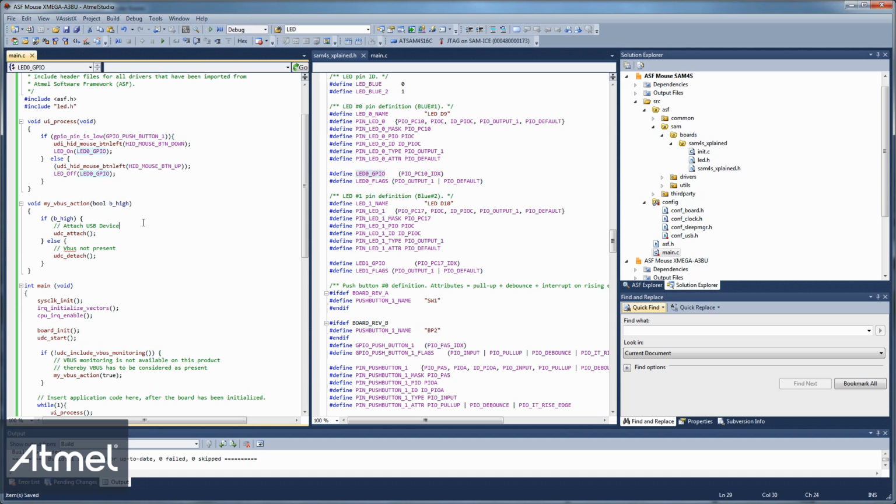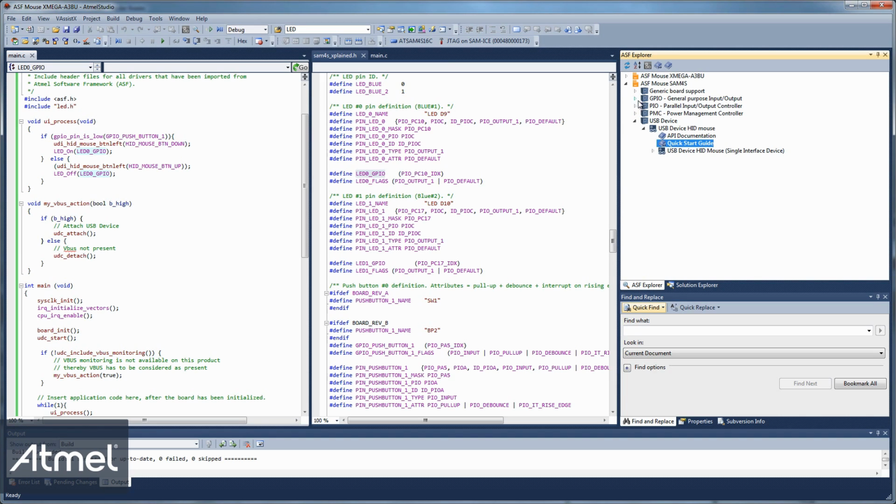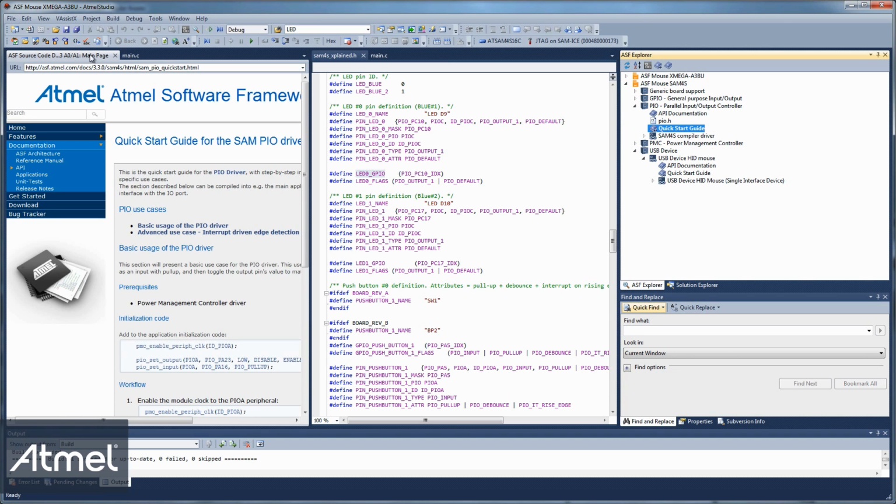In the XMEGA, no special initialization is required before we can start using gpio. The XMEGA has only a single peripheral clock which clocks all the I/O pins. If the core is running, the I/O clocks are running. However, the SAM has a more advanced architecture. Each port on the chip has a separate clock domain. For power saving reasons in ASF, we don't enable them all by default.